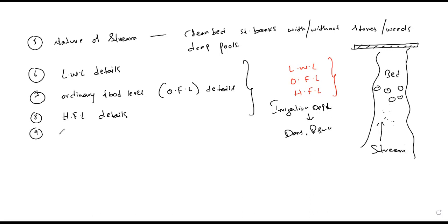And the next one, RL of scour depth. What do you mean by RL? Reduced level. Reduced levels also we need to know for the scour depth of the particular location. And the next one, location on plan of trial pits, borings.